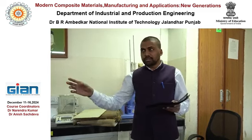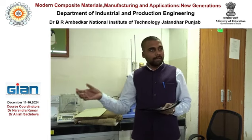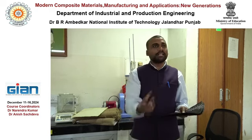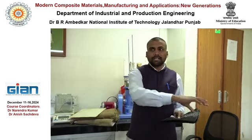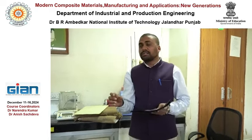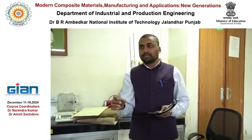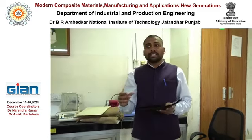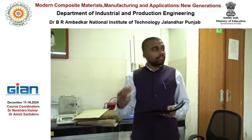For example, the aerospace grade epoxy resins are different. For some automotive composites, for automotive applications, the epoxy resin grades will be different. For some other applications, it will be different. And depending upon the technology also, for example, if you are producing filament wound composite materials, in that case the epoxy resin grade will be different, where the pot life is higher.